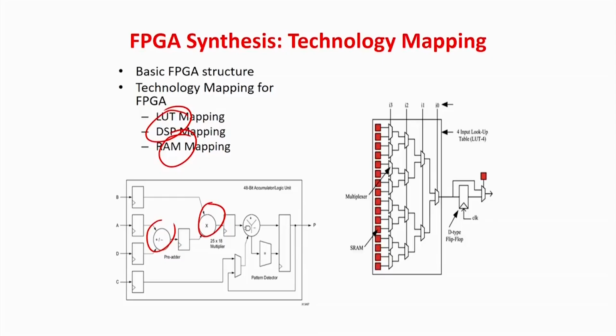So that is now very, very popular, because to go to a fab and fabricate a circuit is a very expensive procedure. As very sophisticated FPGAs are available which can implement even very, very large circuits, a lot of market is coming into the picture. If you talk about academic institutes, more than 99% of the academic institutes believe in FPGAs in the case of digital design. Because students can fabricate, they make an error, they can erase it. Even at the industry level, you are allowed to make mistakes, you can check, you can prototype and verify. So therefore, FPGA is also very important apart from ASICs. So a few lectures will be dedicated to what things will change or what optimizations are required if you are thinking about an FPGA based design.